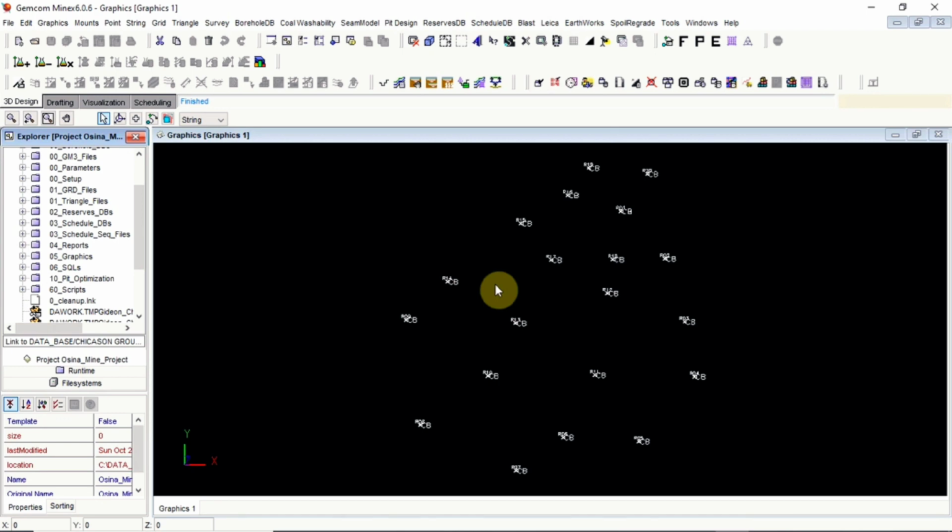Do you understand? So first of all, you will need to start from how to prepare your raw data, how the raw data looks. There's a format your raw data should look like, and there's a way you have to bring them in. So if you don't have your XYZ, that is the polar coordinates, first of all, to start with, before you start anything, you can look at this now. These are the collars. Do you understand? For it to plot here, you have your XYZ. And the issue again here, when you're building your collars, is that the topo you're going to use must align with the collar coordinates. If you are using a topo that has some difference from the collar coordinates, you will have some issues when building your models. So we'll come to that when we deal with it.